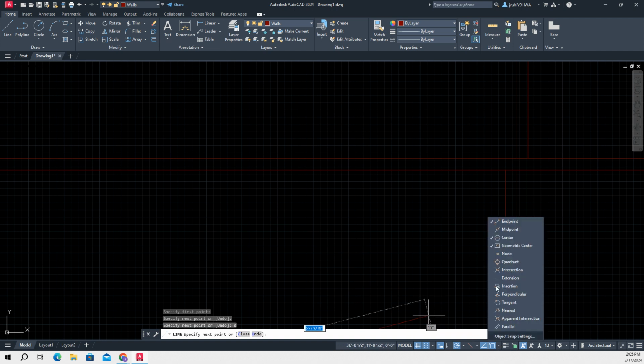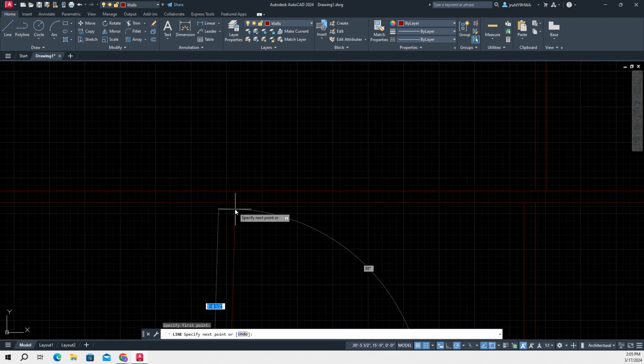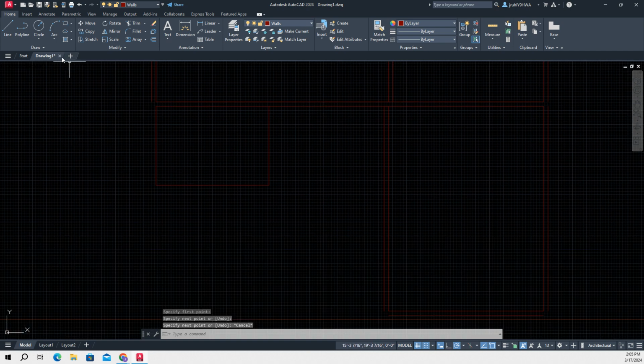Down here, let's see what I got on. I'm gonna turn intersection on, maybe it'll snap to the intersections a little easier. All right, so we're making our way. Going back to offset. I've been doing all the walls, right? So they're 4-inch walls. Enter space to turn it back on. Enter to enter the value. Enter space to turn it back on. Enter. All right.